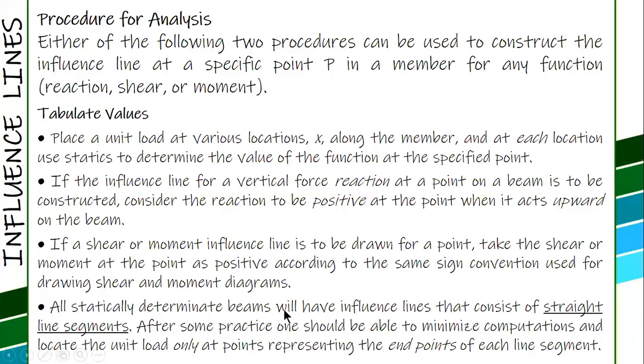And all statically determinate beams will have influence lines that consist of straight line segments. So, all of them are straight lines, as long as it is statically determinate. When it is indeterminate, it is a curved line, not straight.